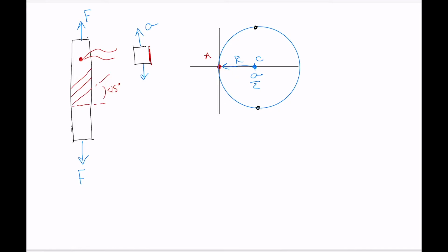So here we can see that the maximum shear stress for an object under only uniaxial tension is located at a distance around the circle of 90 degrees, which is a 45-degree inclination in reality, right? So that's matching up with the direction that these slip planes are forming.